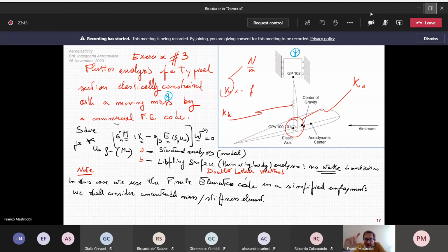And so that coefficient, the phi on the n, is representing a doublet singularity on the surface. For this reason, in the case of lifting surface, we also have a method known as doublet lattice method, DLM. And this acronym is very used in the technical literature.